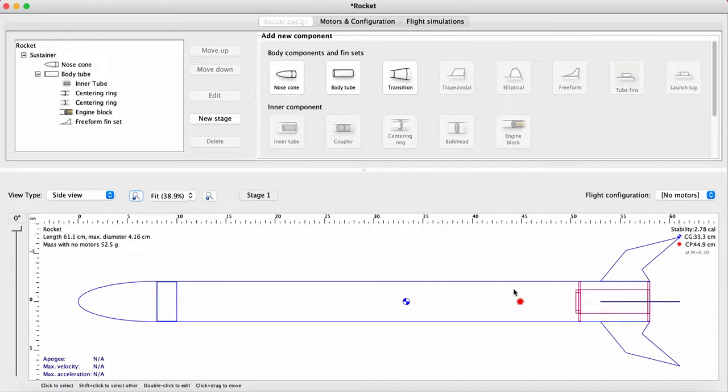Okay, so as you're designing this, look for these two numbers very carefully and make sure the center of pressure is behind the center of gravity. If it's not, then the drag creates a torque which turns the front of the rocket one way or the other, and you get whoosh, or whoosh, instead of nice flowing smooth motion upwards. Okay. All right. That's fins. What's next? Well, we got to create a launch lug, right?